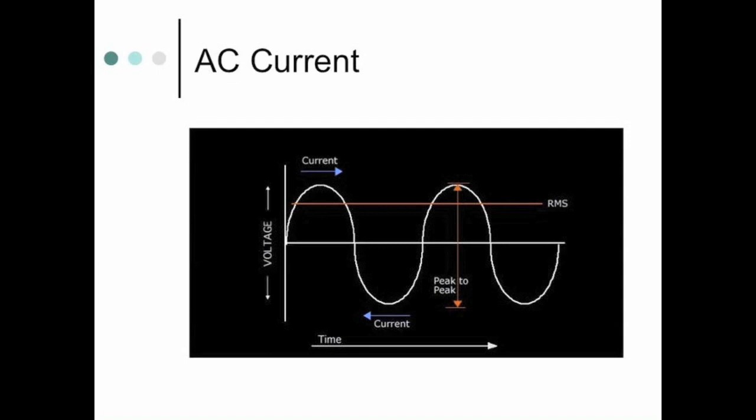The reason is that when you think about all of the power distribution in a city, from the main power plant to all the little substations to the houses, and we talked about what power is, because essentially at the end of the day we want to turn on a light bulb, which is 100 watts, use some power. If we have 100 volts coming out of the wall and we've got 100 watts of work we want to do, that would mean we need 1 amp of current flow, right? 1 times 100 volts would be 100 watts.